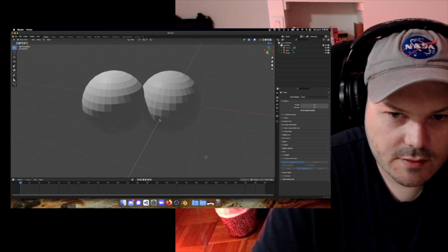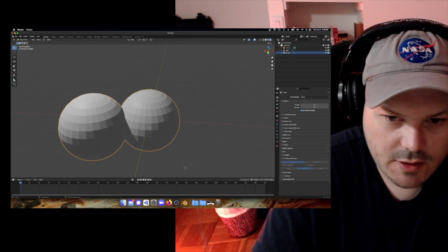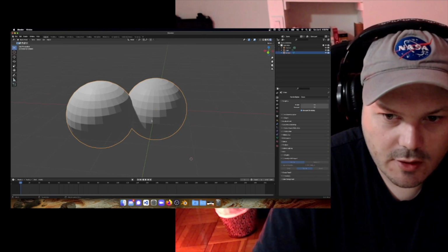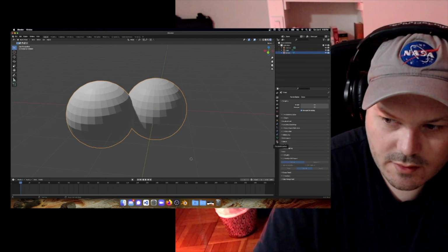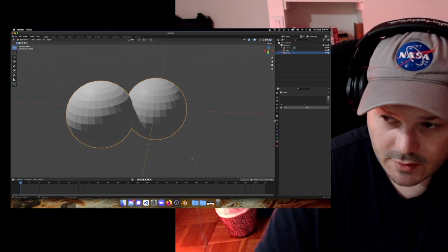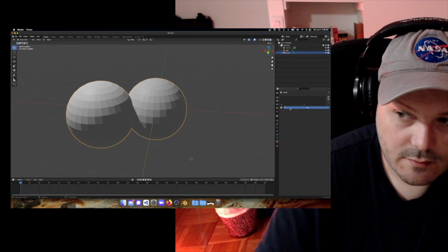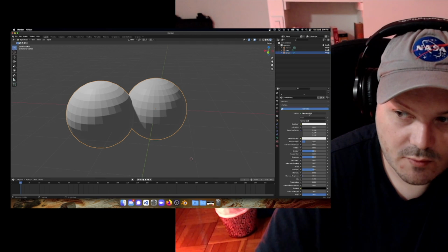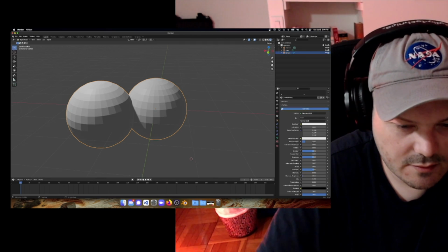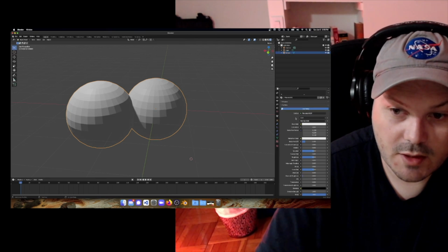Alright, so let's just do a few more things. Let's add a material to one of the objects. Actually, we only have one object in the scene, so I'm just going to go into the materials tab here. You can see when I hover over it, it says material properties. There's nothing going on right now, but what I can do is just create a new material. Boom. And by default, it creates a Principled BSDF shader. This is perfectly fine. It covers so many different things.